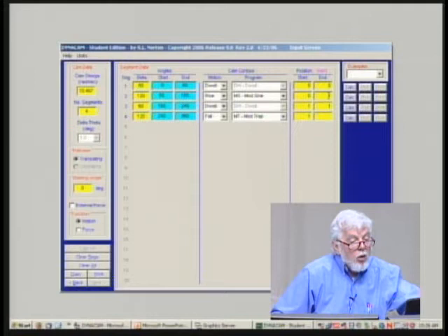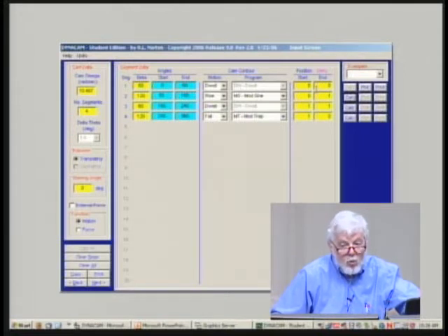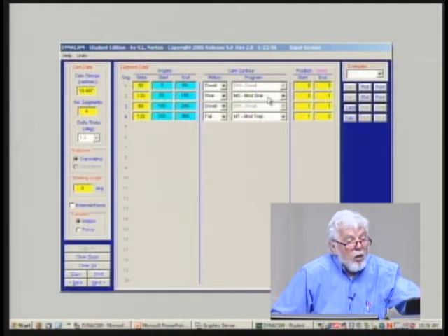If I put it at 1 at the top of the hill and it knows there's a dwell there, it'll keep it at 1 for the dwell, and it's now about to come down the hill on the fall, so the 1 has been put there for me, so I'll bring it back to 0. So now I have all the information there necessary to calculate, and you may have noticed that these buttons were dimmed before and now they're not, because once you have complete information in the row, I wake up the button so you can do a calculation. If I hit that, it calculates the dwell, which is just a case of putting zeros in all those buckets. That's pretty trivial. This one goes and calculates the modified sine for the SVA and J for me.